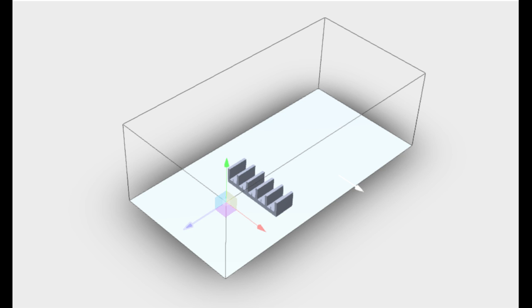The heat sink was placed inside of an enclosure with an incoming air velocity of only 0.5 meters per second at 20 degrees Celsius to simulate simple electronics with only a small fan to provide airflow to the entire case. It is not intended to model an electronic component with a dedicated cooling fan.